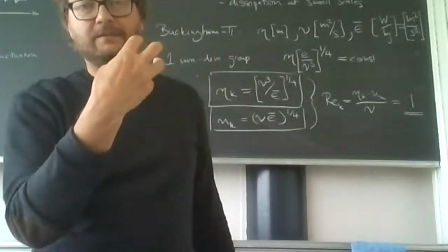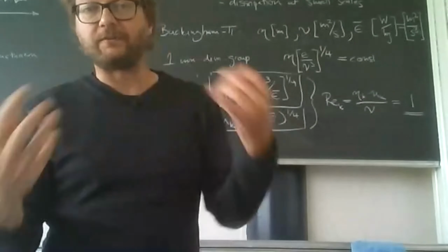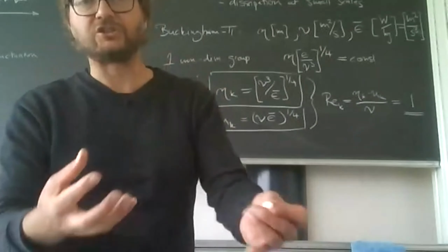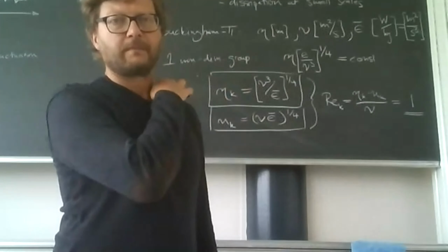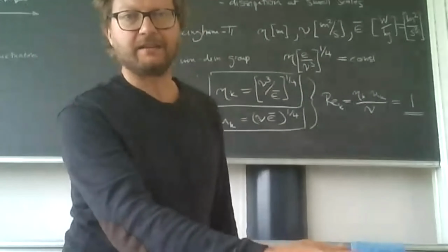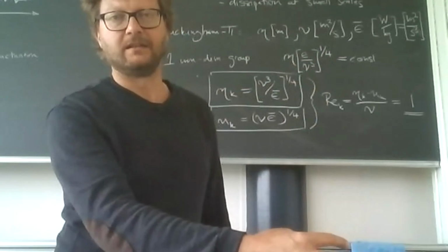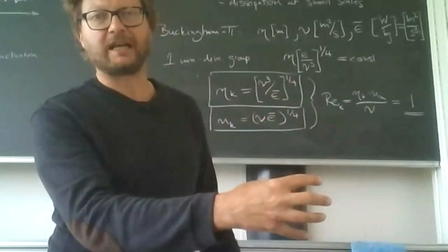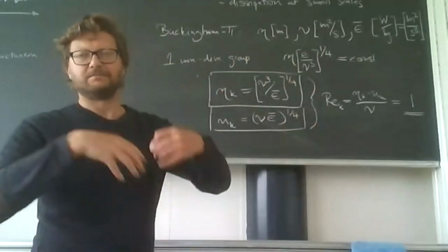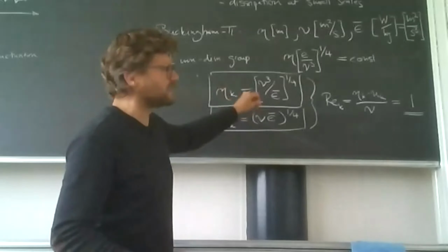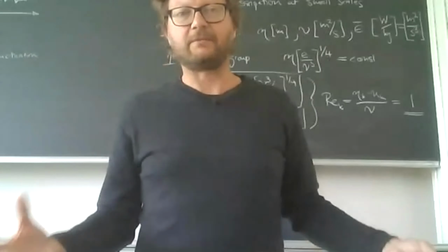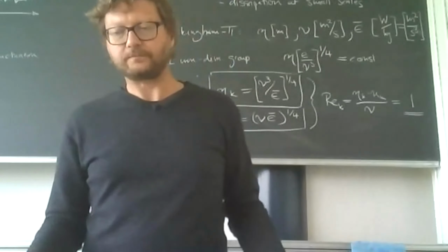So this is really where viscosity starts to dominate. This is why these vortices are very, very dissipative. This is where energy is dissipated into. And there's not really anything smaller than that, because anything smaller than that has dissipated before it can get smaller. So this is pretty much the end. These are the smallest scales that we can find in turbulent flow.